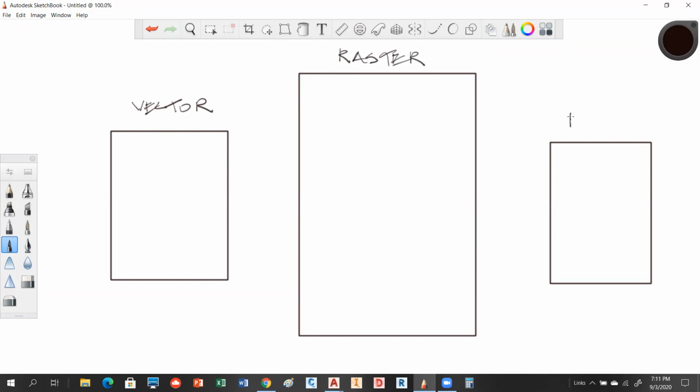And your screen, if you've ever looked at your screen, say with a magnifying glass, you will see that that's a bunch of dots as well. So when you draw a line in the vector database, it looks like a line, okay? In your raster, it kind of looks like that. You know what I'm talking about, the stair-steppy look. And the screen, it may not look like that, but it's also kind of jiggly like that, okay? So with AutoCAD, you're working in a vector format, and this is where your 14 sig figs are, and it's actually real numbers, but rasters are integers.